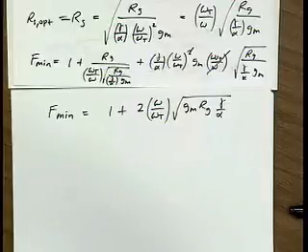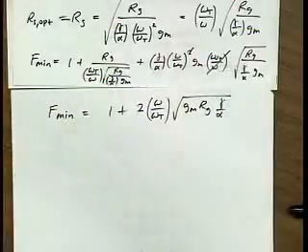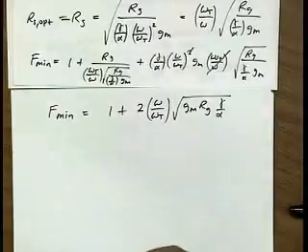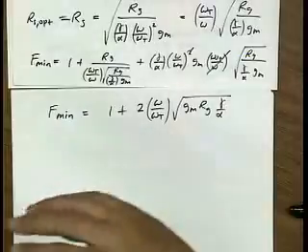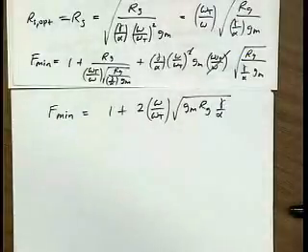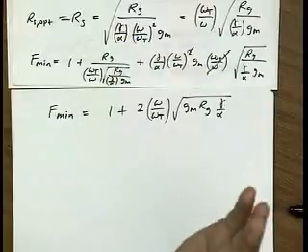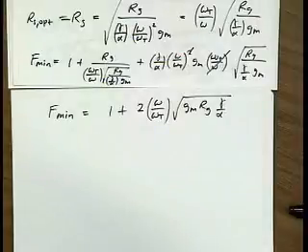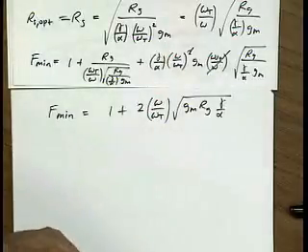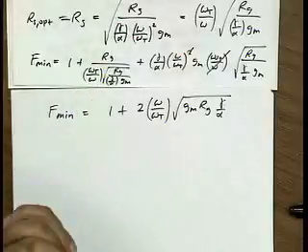Okay. So noise figure is a function of source resistance, right? Now usually for a system, when we measure it, we like to measure it with a 50 ohm source as a standard. But not all systems work with 50 ohms, right? If you're in a communication system, you use 50 ohms. If you're in, let's say, a low frequency system, you may prefer to use kilo ohms for your source resistance, right? So the concept of noise figure strictly doesn't depend on source resistance, right? As a concept, noise figure tells me how much my signal to noise ratio deteriorates as I go through a block. And it's independent of source resistance.